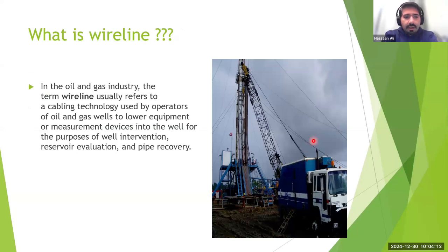So, what is wireline? Wireline is a term that has very different meanings across the industry. But in oil and gas industry, the wireline actually means the cabling technology that is used by the operators of oil and gas wells to lower different type of mechanical, electrical, electromechanical, and electronic equipment into the well for the purpose of well intervention, reservoir evaluation, and pipe recovery.